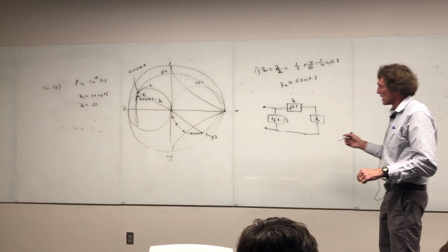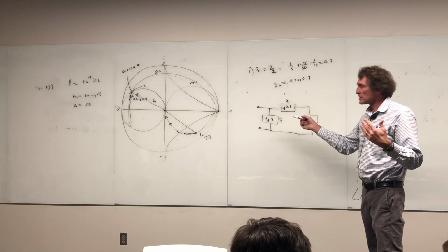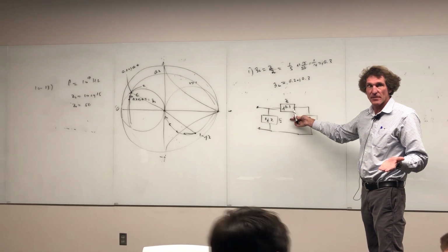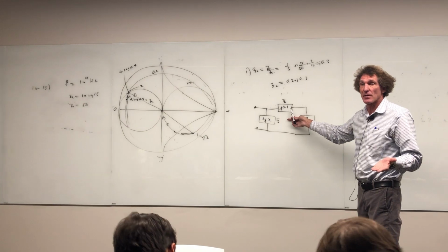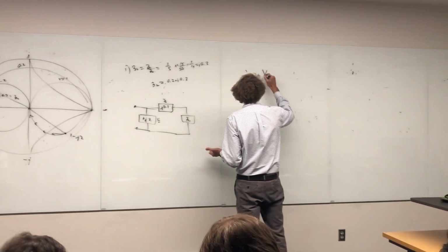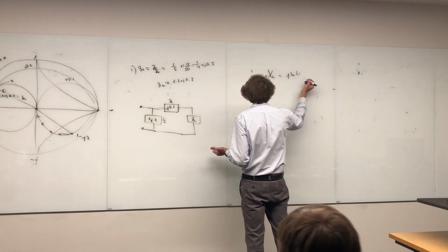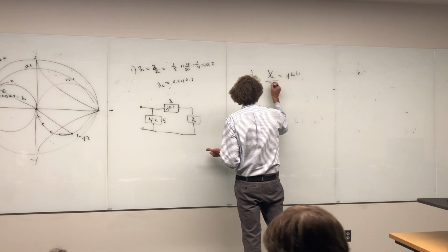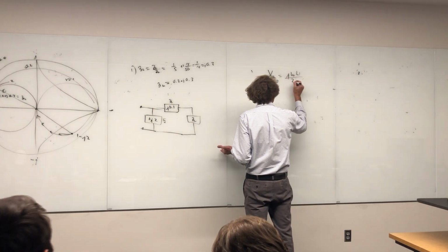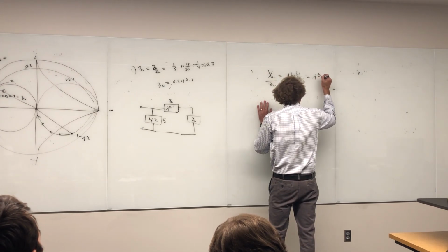And then we're impedance matched. Okay? With me, let's go and try this on your own. First, that's an impedance. If I want to get the value, and it's an inductor, correct, class? So we start with the impedance of an inductor. That's j omega L. Then we normalize it, and set that equal to j0.1.